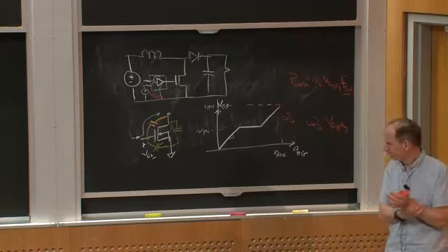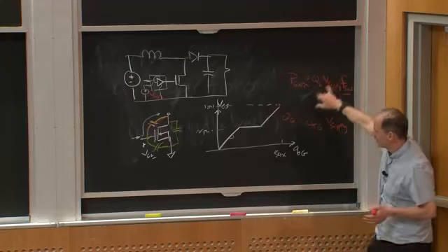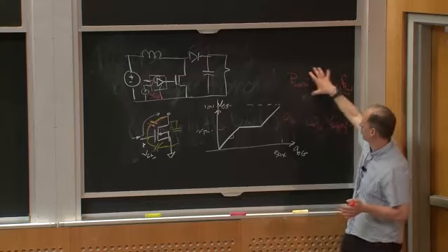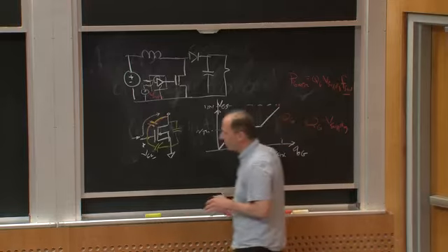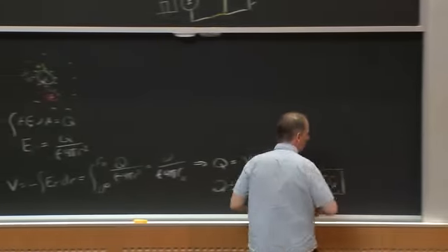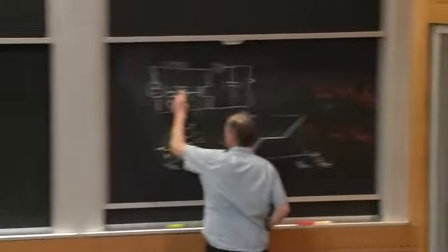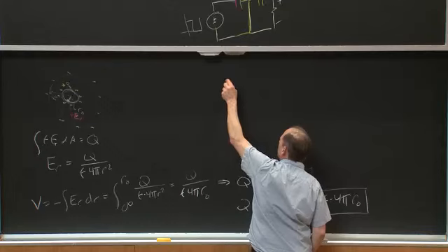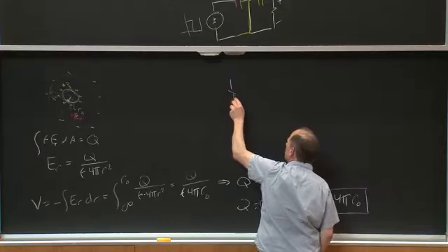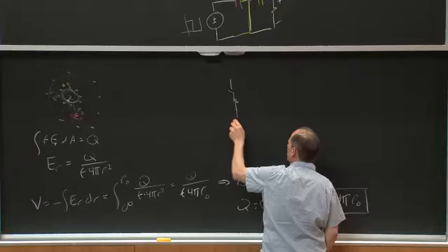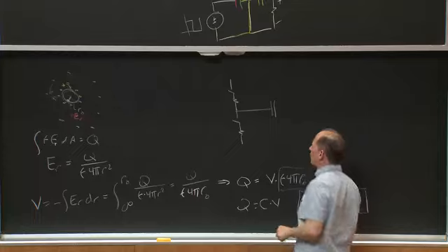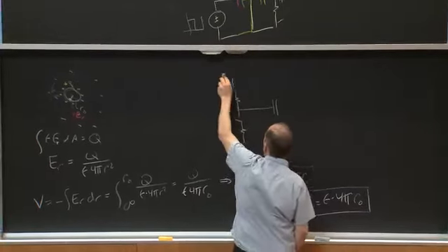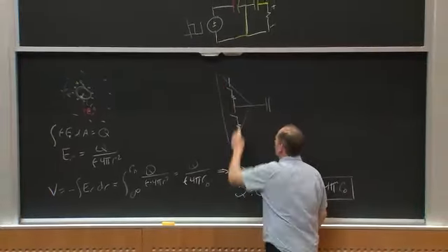So that's one thing I want you to pay attention to: you've got to really look at these threshold curves to get your total loss. There's another thing you might want to think about when you think about the driver itself, and that's the following. What would this driver look like inside? Inside, you might model this driver as one MOSFET and another MOSFET, and then it's connected to the gate that it's going to drive. So this is my gate driver. I'm going to turn on the top one, this is V supply.